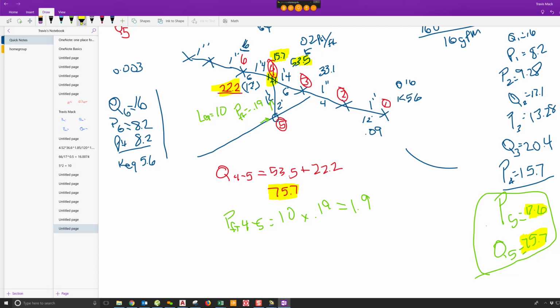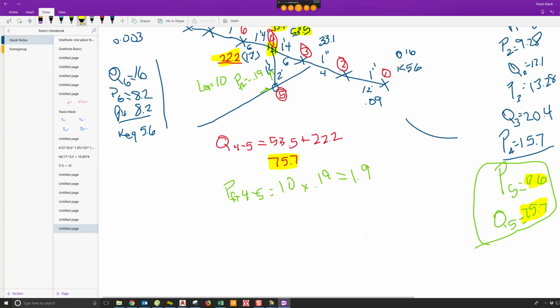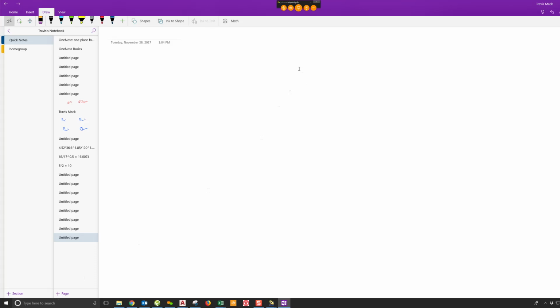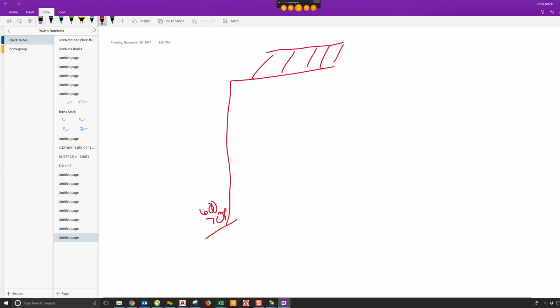Yeah, and if you kind of see how this starts to come into play, here's some practical scenarios for what you guys do. Let's say we've got a manifold, we've got an overhead system here, let's say it's some grid. We're doing a warehouse here and we need 70 psi at 600 gallons. Now I've got a rack system over here where I'm feeding rack heads. If I calc this so that this needs, say, 90 psi, well, you know it's going to balance to the higher pressure. So I would be over discharging my overhead system by 20 pounds. I'd be flowing a lot more water out of it.